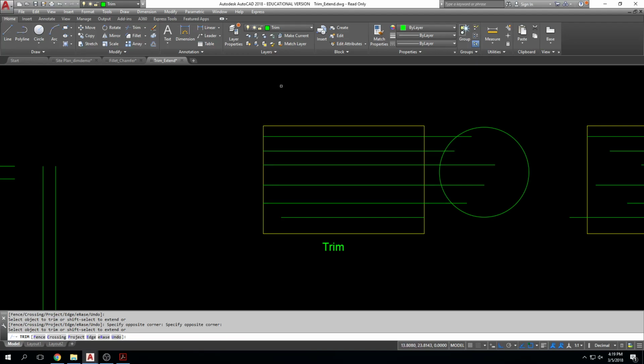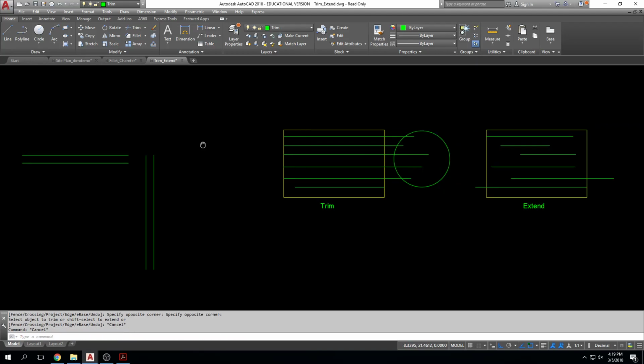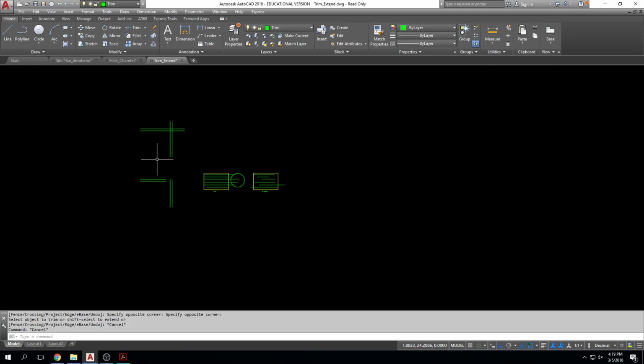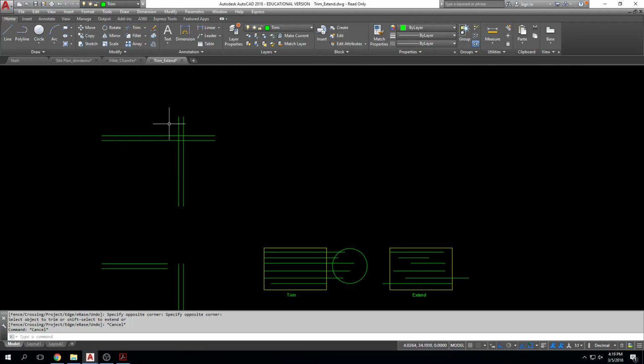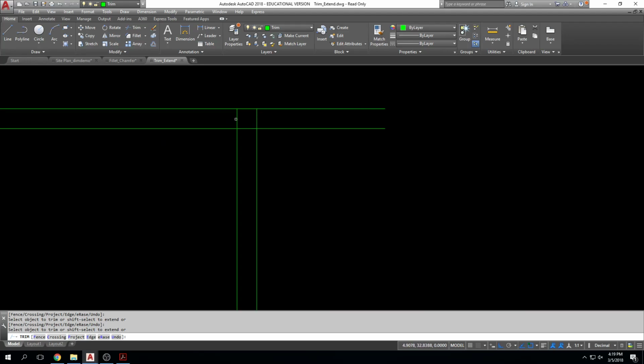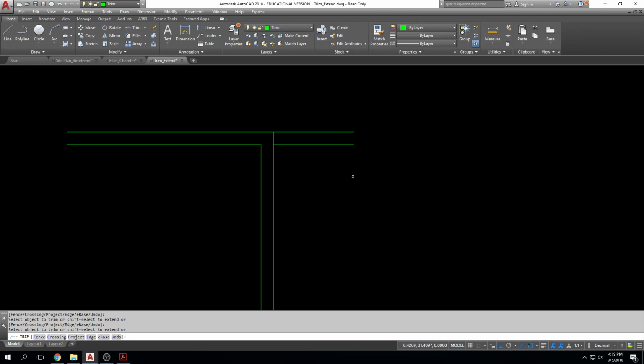I think the most common thing that you will be trimming for now will be just your walls, right? TR, enter, enter, click, click. If you'd offset a polyline to create your walls and there were these messy pieces inside, click, click, escape, escape. Now this line right here I can't trim with TR, enter, enter, because it's just a piece of line. It's not overlapping anything.